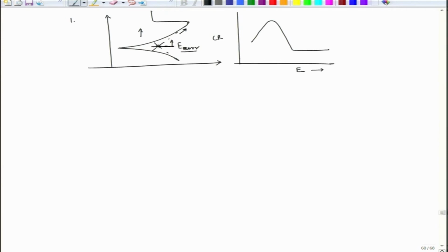Initially the corrosion rate is Icorr, and this is the variation of Ia. Ia reaches the maximum, then drops and maintains a constant segment as the potential changes constantly. So, this is one nature one could recognize.